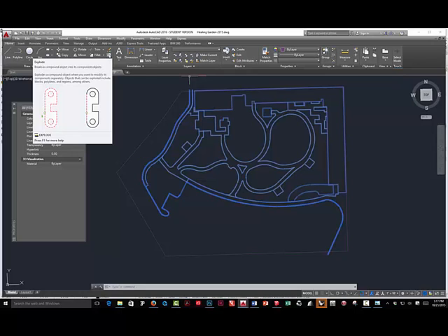But if you have curvilinear walkways like this, and you just export this right now and bring it into SketchUp, it will come in as a whole series of tiny little line segments. And that may work, but it may not. It makes connecting them into surfaces more difficult. And it also means that you can't change the size of those arcs. If it's not smooth enough and you want it smoother or you want it rougher, if it comes in as segments and not arcs, then there's nothing you can do about it. What you get is that's it.